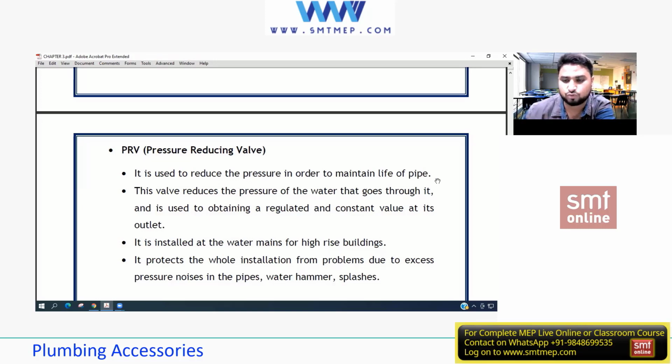As I said, velocity plays a major role in plumbing, because you deal with different types of flows, and we'll be seeing that also. We have two types of flows, turbulent and laminar. Laminar is smoother, turbulent is with high velocity. High velocity with bigger diameters of pipe is not recommended. If the velocity inside the pipe is higher, the life of the pipe or the material will be reduced for sure, isn't it? Yes.